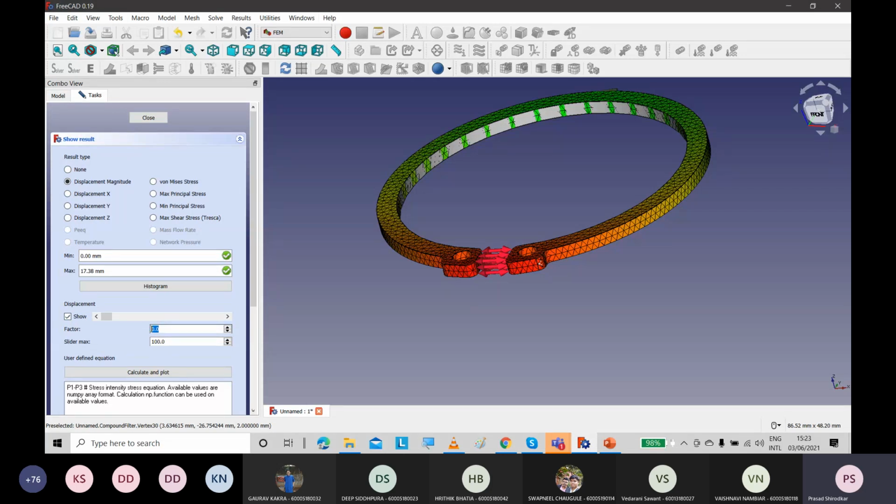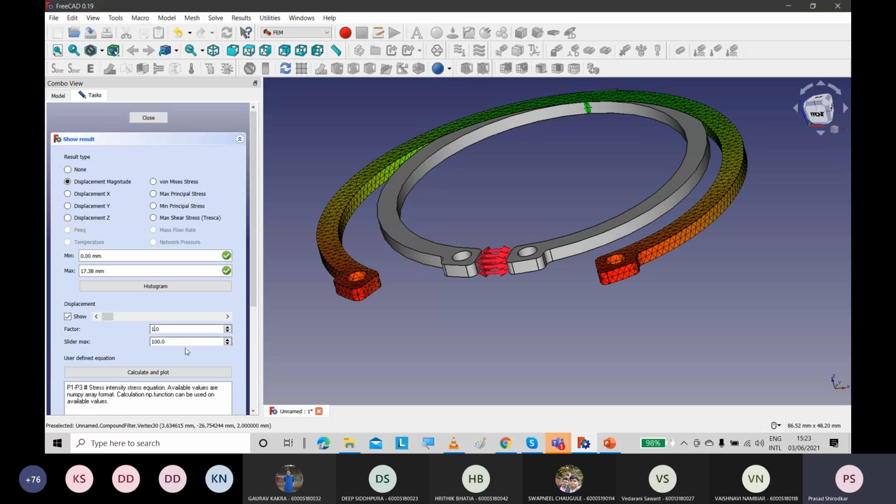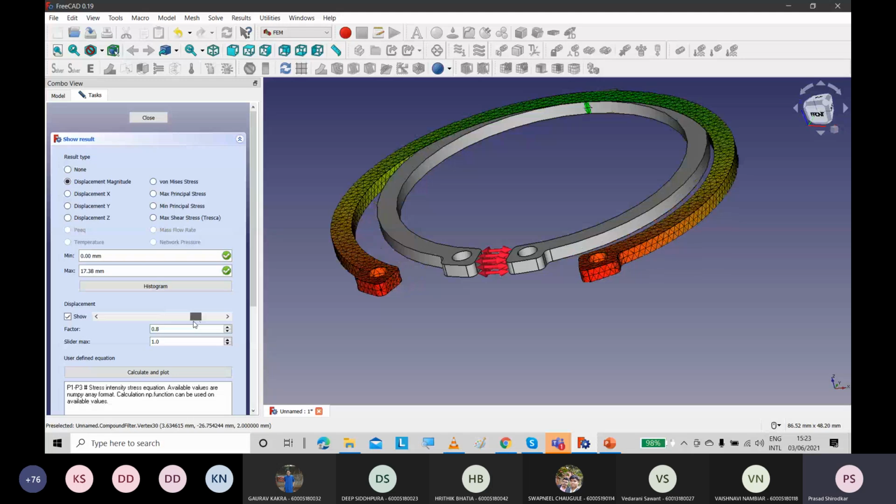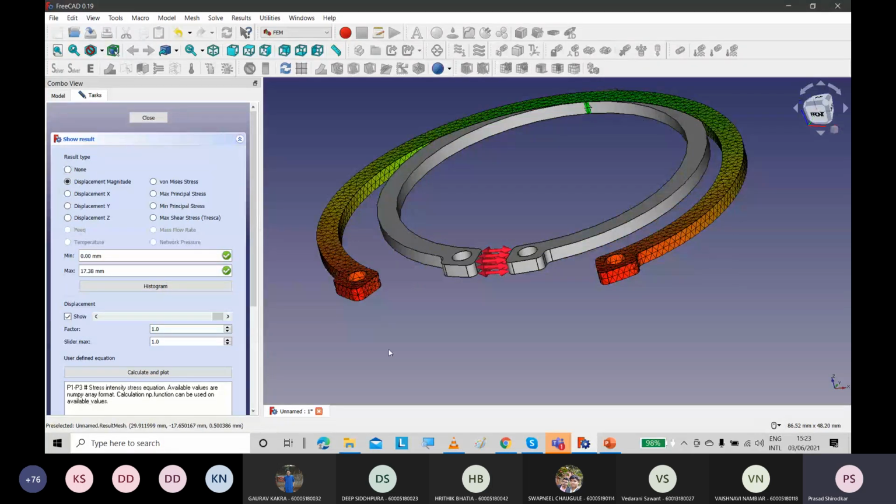Okay, you can also just do this and click on change this factor to 1, this also to 1, and so this will give you, as I increase the snap displacement on the snap ring, how the stresses are generated.